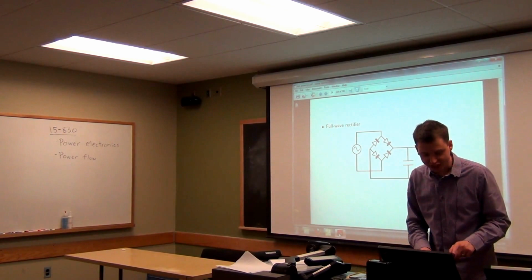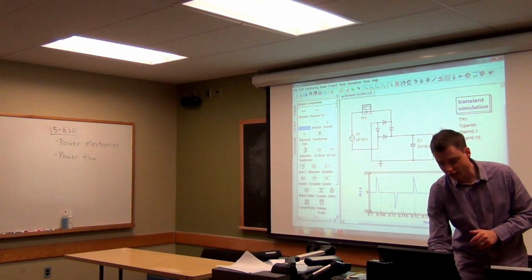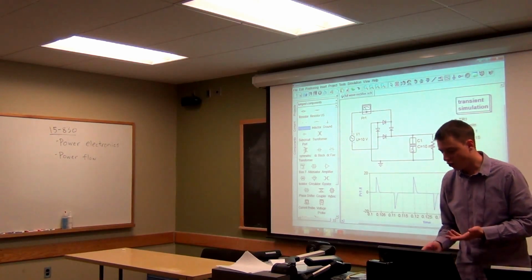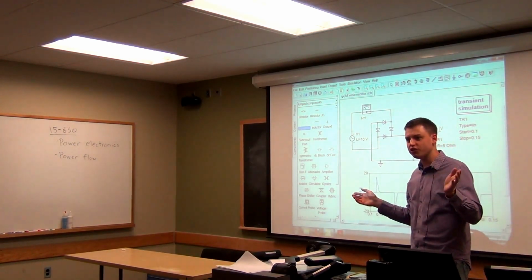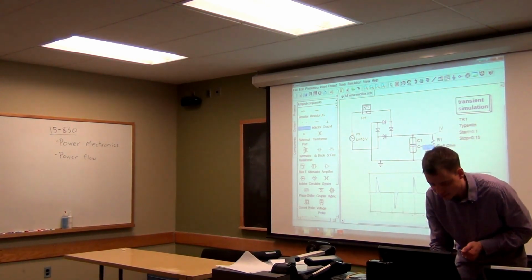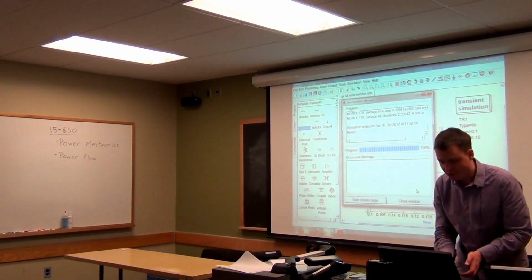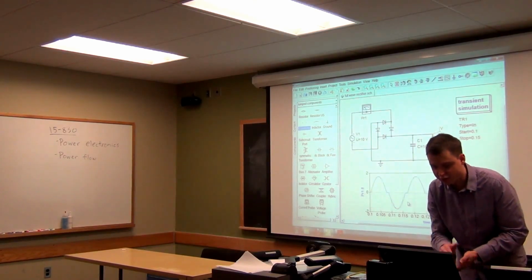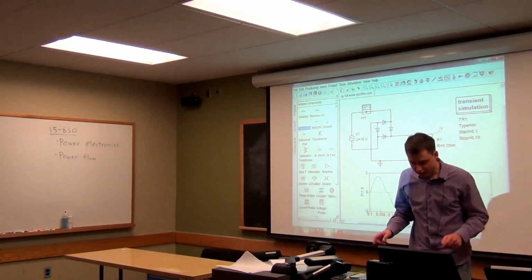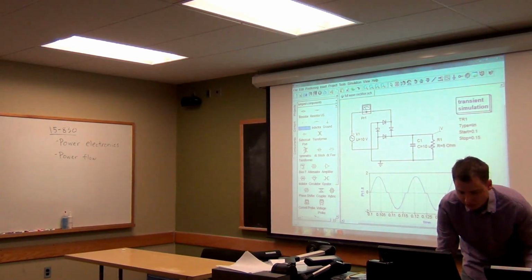Let's maybe actually just see that again. So if we have this rectifier here and we don't have the capacitor. So say our electronics can use different voltages a lot more. It still needs a DC source, but maybe we just have a lot less capacitance here. So let's make this 10 microfarads instead. It looks much more like this, but there's this little time the diodes block it for a little bit of time, but it has some sort of waveform like this. I believe that this guy looked kind of similar to that. So let's look at what this looks like actually.